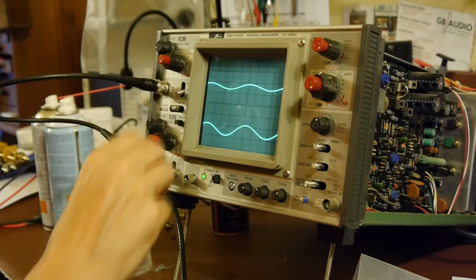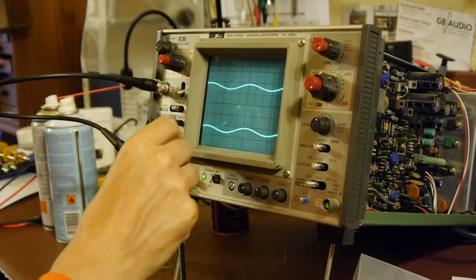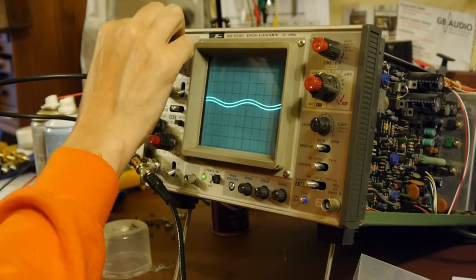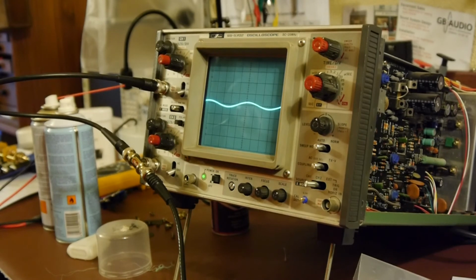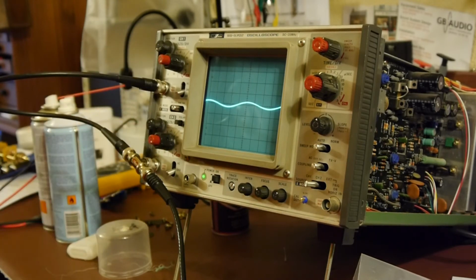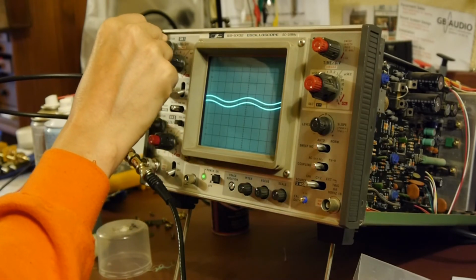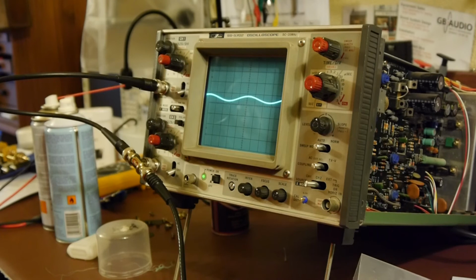Okay. So let's go on 10 volts per division, and let's put these traces on top of each other, so we should be able to get an idea if the calibration is okay. So that's not too bad. We're on 10 volts per division at the moment, channel 1 and channel 2, and we've got 5 volts peak to peak in. So we'd expect that to be about 1 square high, wouldn't we? And it looks a little bit under that at the moment. It's under a square, so maybe there's a little bit of tweaking we need to do.